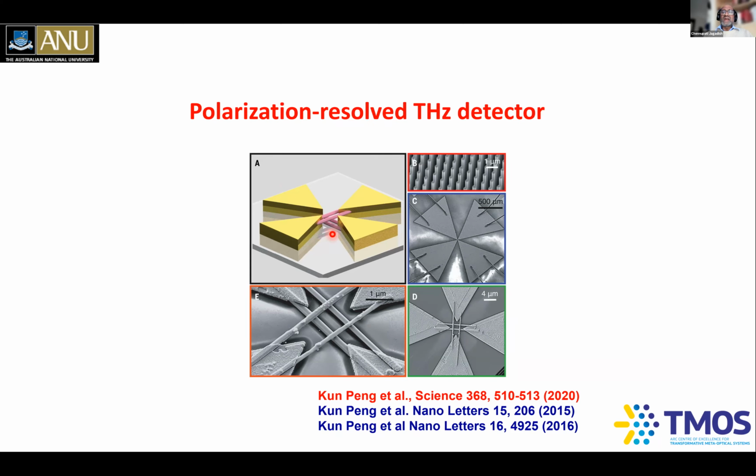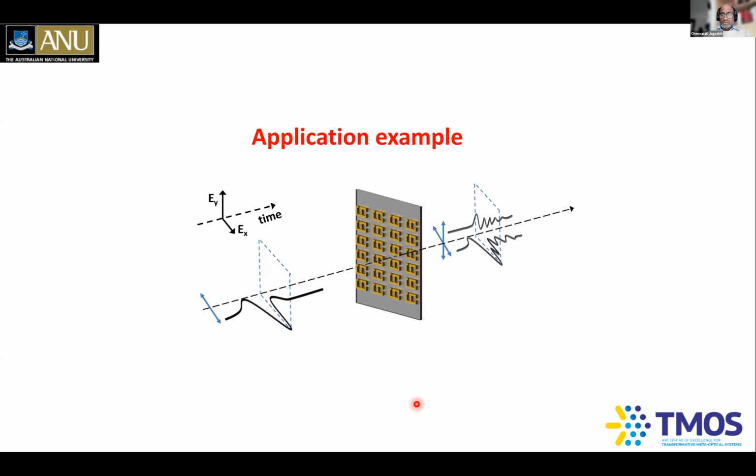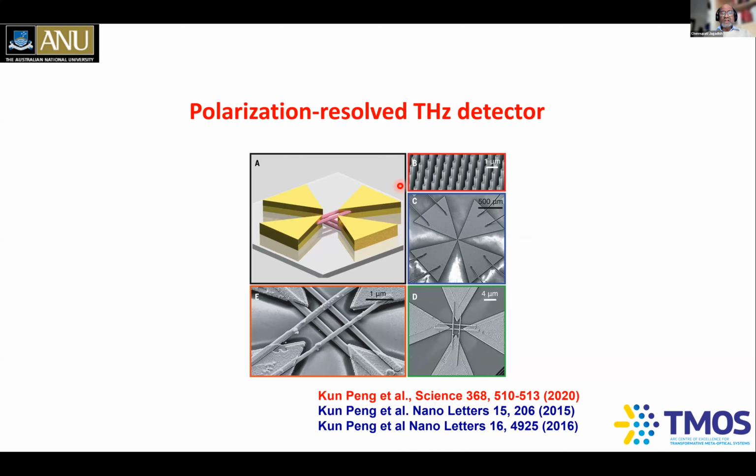And it turns out that the antenna design plays an important role in terms of the bandwidth of the terahertz detectors. That's what she determined during her PhD. Then she tries to put another set of nanowires perpendicular to the ones at the bottom here. The challenge has been to avoid contact between the top nanowires and the bottom nanowires. If they're physically in contact, they short circuit the device and you will not be able to measure the polarization resolved terahertz detectors.